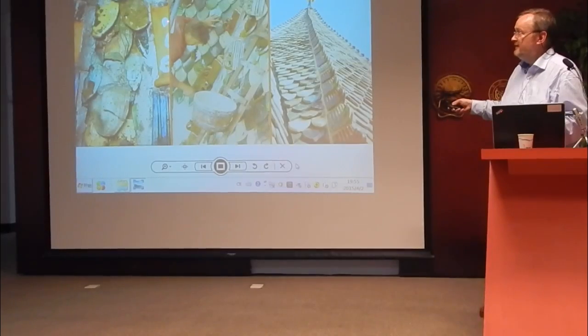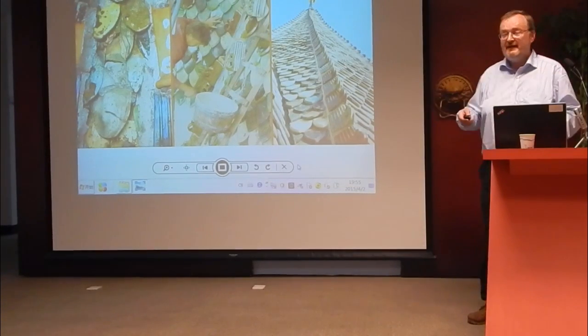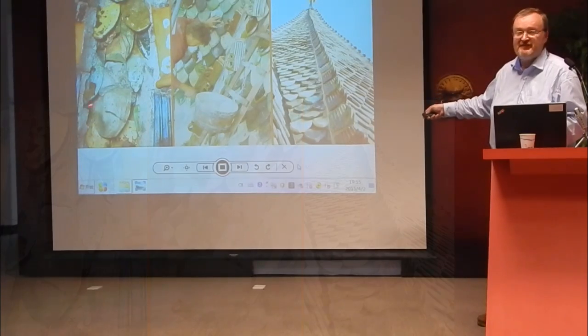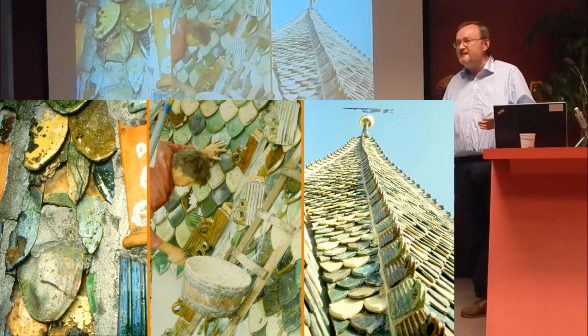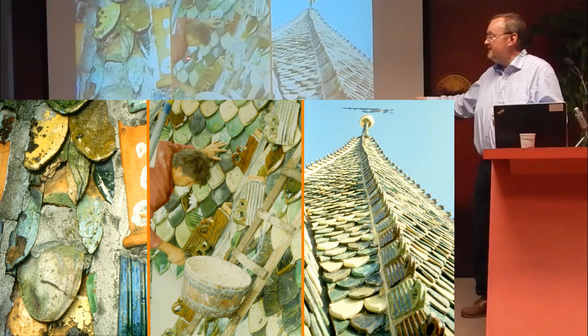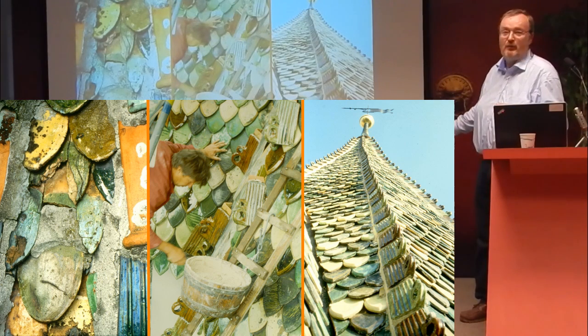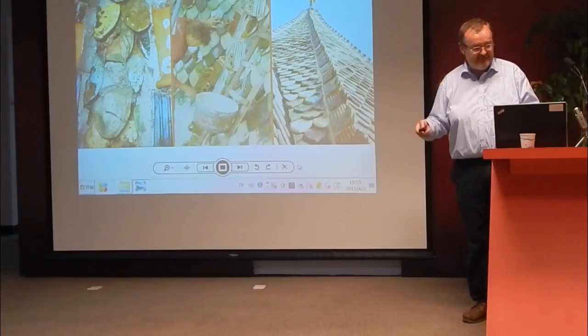That's from a friend of Bruno Siegelin, a late Gothic tower with colored tiles. And here the historic construction comes down because of the cement mortar. The cement mortar damages the rain tightness of the roof, and we repair with poor lime mortar. And it works. If you know how lime mortar works, it will stand the frost and the rain.